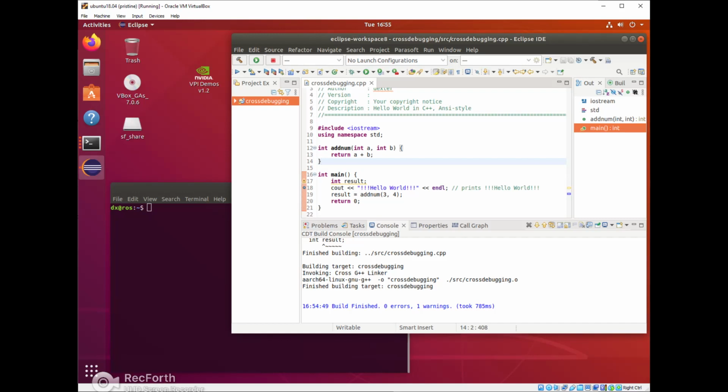Well, first, since this is an ARM64 architecture, clearly we cannot execute this locally in our machine. So we need another ARM64 target board running, because we're gonna copy the cross-compiled binary there. I mean, we are not going to do that, but the IDE will do that.